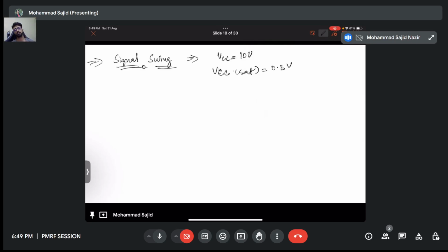So your potentials at VE minus VC should be within this range. First, let me draw a reference of 10 volt, which is the maximum VE can go without going into the cutoff region. Because if VE is equivalent to 10 volt, current will drop to 0.